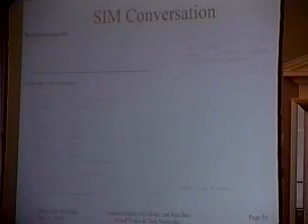Here I want to read a dedicated file. There is a dedicated file, which is like a subdirectory just for GSM. So again, we can decode the answer that comes back and it tells us about that file. Here's an example of how to read the subscriber identity out of it. You ask for what's called an elementary file, which is kind of the lower level leaf file. And it's got the same kind of header, tells you the information that's going on. And down at the bottom, we actually read it. We issue the read command and we get the IMSI back out.